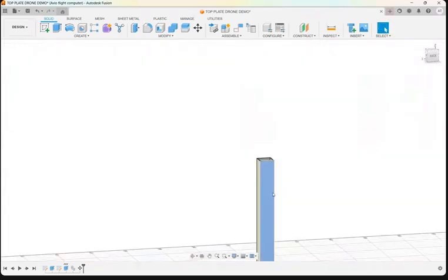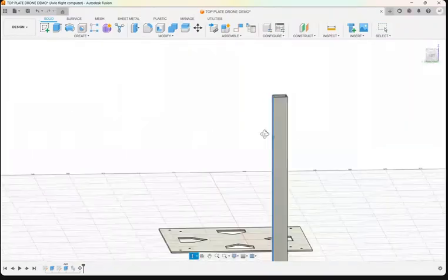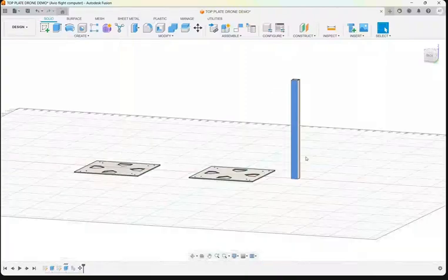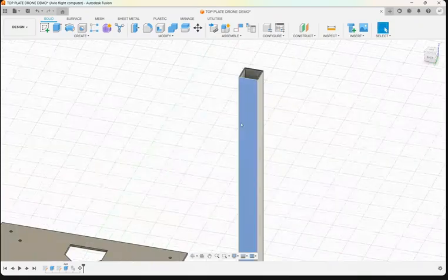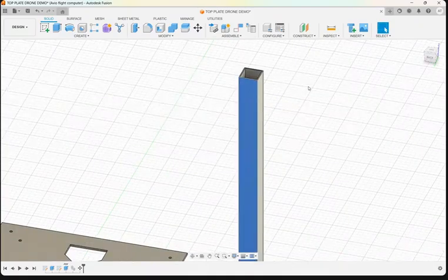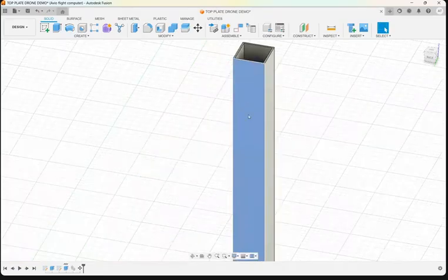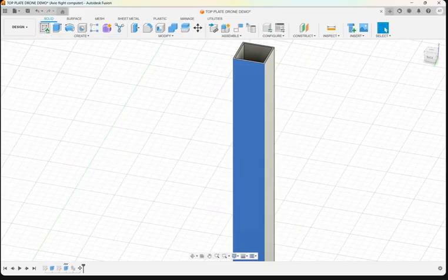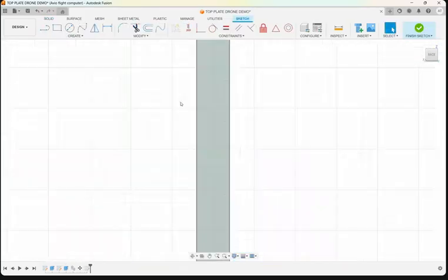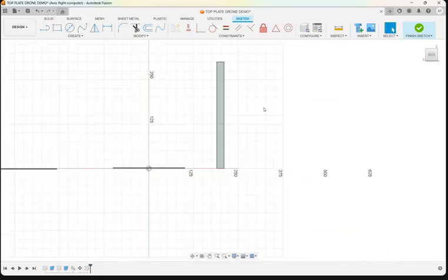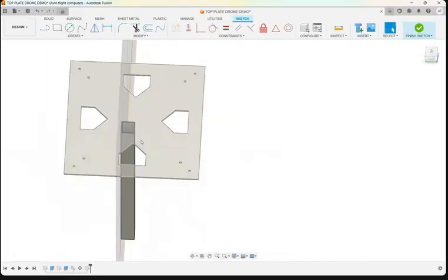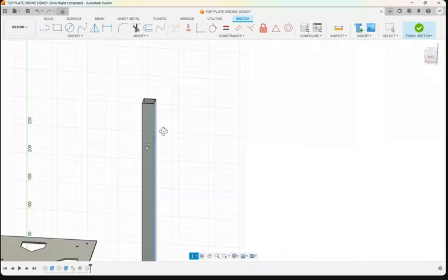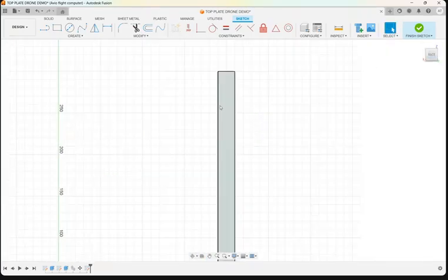So what we'll do is select the surface we want to sketch on. Now the sketch we make will not be on a plane. Instead, we'll sketch on the body that we have already made. We'll select the face we want to sketch on. After selecting, we'll click the sketch button and it will open up the area and make a plane on the surface of this face. So now we can sketch over here.